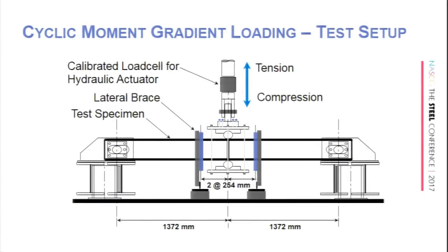Before we go on, it's really easy to push a beam until it achieves that load-deflection, load-rotation curve, whatever you want to call it. But if you want to do this same beam cyclically, or at least quasi-cyclically or quasi-statically, now we are going to push and pull on that beam. So the experiment gets a lot more difficult. Why do you think we needed these big slotted end fixtures here?